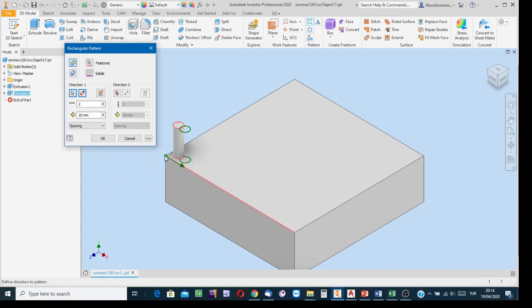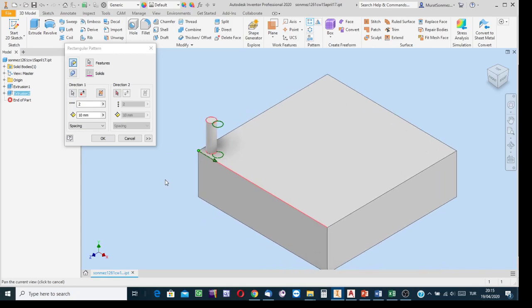If the direction for the copies is wrong, you see the green arrow, it appears after clicking the direction button and then indicating a certain reference to say parallel to it. You see such a simulation, a green arrow. It indicates the sense for the copies. If it is the wrong direction, then flip it. Click on this and reverse the direction.